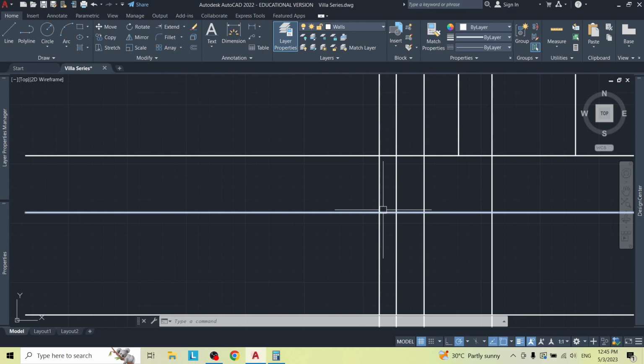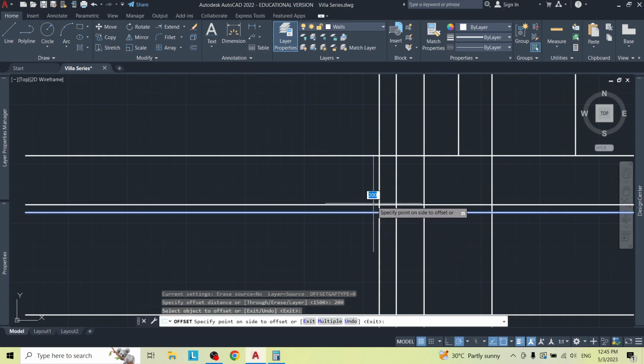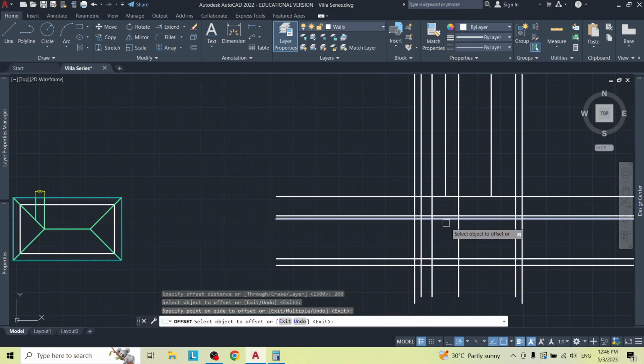So we're going to offset the height of the fascia board, which CXC might give you. The fascia board might be a 2 by 8 or 2 by 6. We're going to use 8 inches, so that's going to be 200 millimeters. So I'm going to offset 200 millimeters upwards for this line. Remember, this is my fascia board, our overhang line.